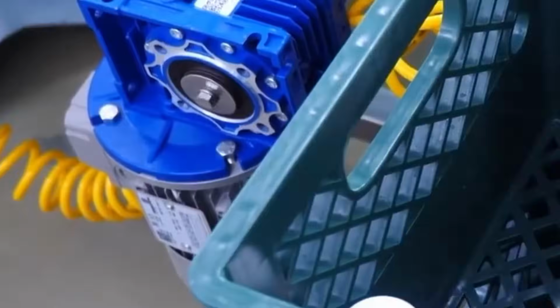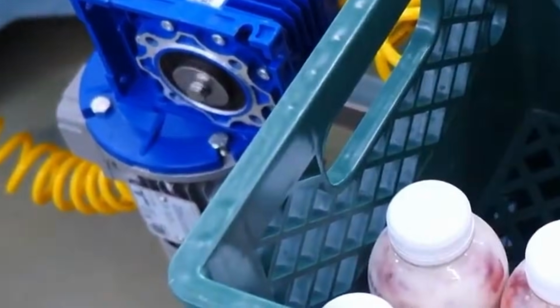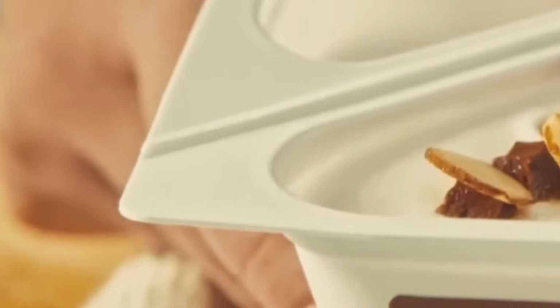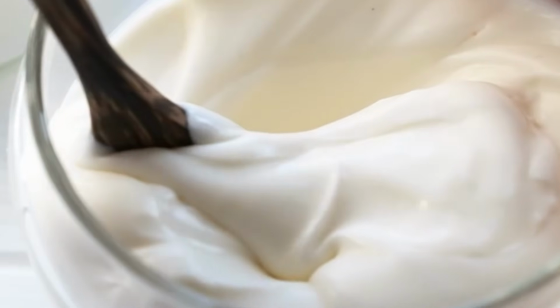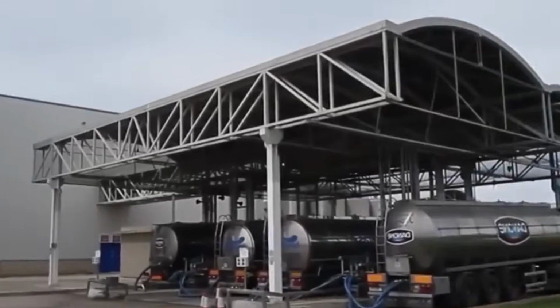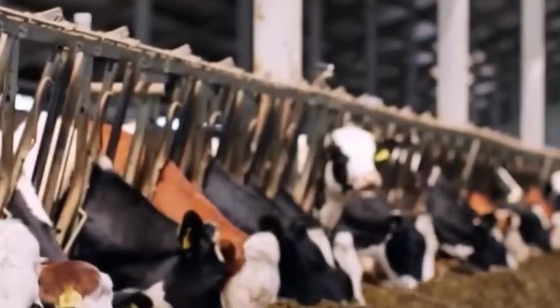From here, the yogurt base may be held in intermediate storage for up to 24 hours before being processed further. If flavorings or colorants are required, they are added post-fermentation to preserve the viability of the live cultures. These additives are introduced through inline dosing pumps, controlled by magnetic flow meters for precise delivery. The chilled fermented yogurt mix is transferred to the continuous freezing units.